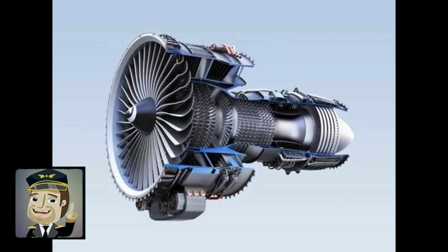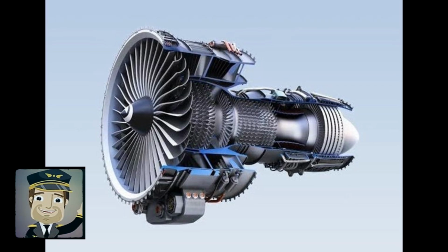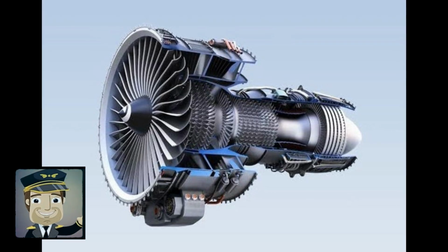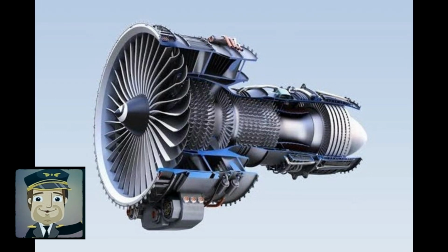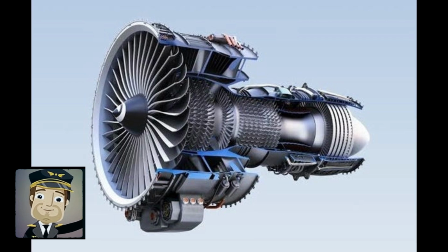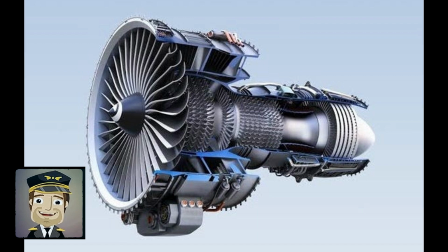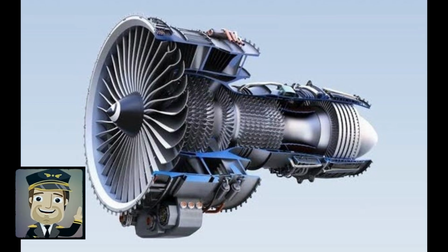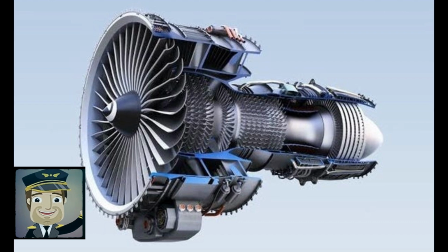In summer 2017 at NASA Glenn Research Center, a team finished testing a very low pressure ratio fan on a PW1000G, resembling an open rotor with fewer blades than the PW1000G's 20. The weight and size of the nacelle will be reduced by a short duct inlet, imposing higher aerodynamic turning loads on the blades and leaving less space for soundproofing. But a lower pressure ratio fan is slower.